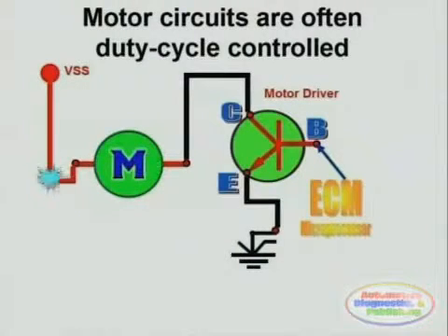And always remember that duty cycle control circuitry has to be performed by a transistor. Relays cannot be used to duty cycle control a component, since the switch rate of a mechanical relay is not fast enough for this duty cycle signal to go into effect.